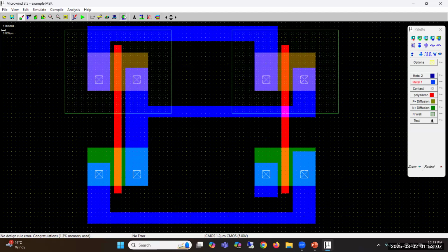Yeah. So the next step is to connect the VDD and the ground. If you look at this, where should we connect the VDD? This is the source of PMOS, right? And this large blue layer is our source of PMOSes. These are connected. So the VDD from here, we will bring the VDD and connect it here.